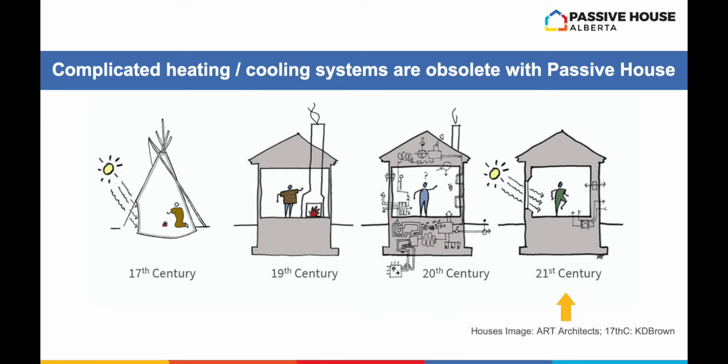What Passive House provides is a much better envelope, much better air sealed, airtight. You let some heat in through the windows in the summer, so you need a much smaller, simpler mechanical system to meet your remaining heating needs and your ventilation needs. When it's simpler, there's fewer moving parts, fewer things to break, less maintenance, and it costs less.